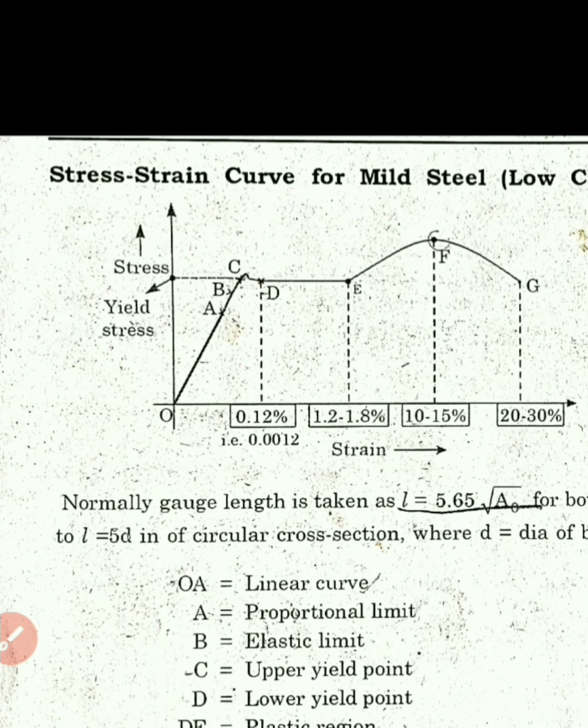See, what happened is, even with a small value of stress, the material is moving towards rupture. When the neck is formed, you can see in your day-to-day life, whenever you have a stick in your hand and because of some reason the diameter in between is reduced because of stretching or something else, even if we apply a small value of force, the stick gets ruptured. So the same happens in steel also. After the necking region, the tendency of the material becomes more to move towards the rupture side, right?